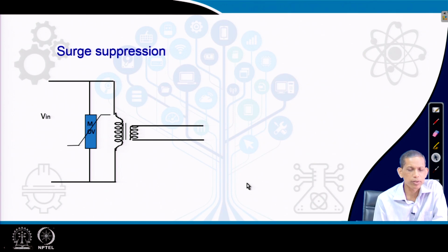In addition to that, to protect the systems from lightning or surge voltages, the metal oxide varistors (MOVs) are considered, connected on the input side and also in the output terminals of the analog connectivity to the numerical relay.